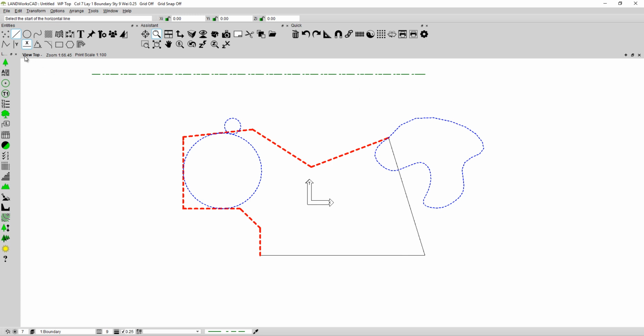And in the same way, the y-axis line is always forced to be in the y direction. Even if I pick something like a circle to start my line on, you can see that my line is forced to stay vertical no matter what I do. So that too can be quite a useful function. However, let's assume I wish to draw lines without actually using my mouse to navigate around this particular drawing. I'll choose the Insert Line command.